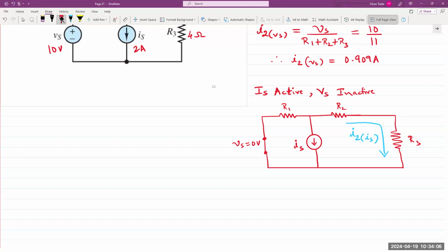If you look at those power supplies, again, for those of you who are taking the lab, next time you go in the lab, there should be a small indicator or a small display with the words CV and CC. CV stands for constant voltage mode. CC stands for constant current mode. Almost all experiments in 251, we use those as voltage sources. We do not use them as current sources. So that's the only difference.